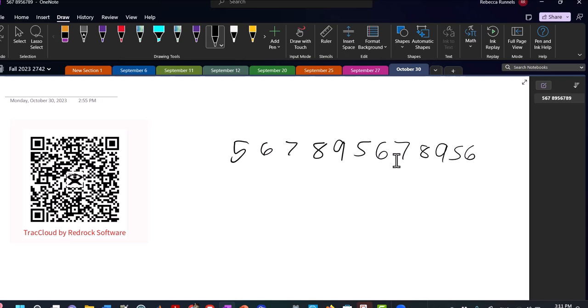Okay, so what you would do there, you build a counter, and all a counter does is go in order 0, 1, 2, 3, 4, up to however many bits you have it set. Say you've got 4 bits. 4 bits would be 16, which would go from 0 to 15. And then after 15, the next one would be 0. 1, 2, 3, 4, 5, 6, 7, 8, 9, 10, 11, 12, 13, 14, 15, 0, 1, 2, 3. But if you wanted to have a different pattern, you would load 5. So in this case, I would load 5.